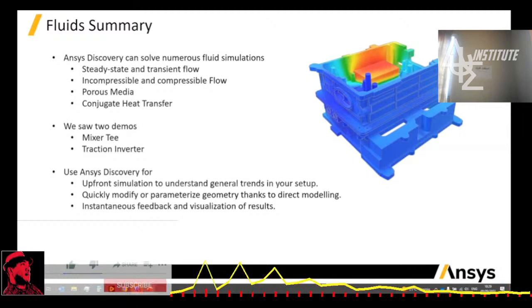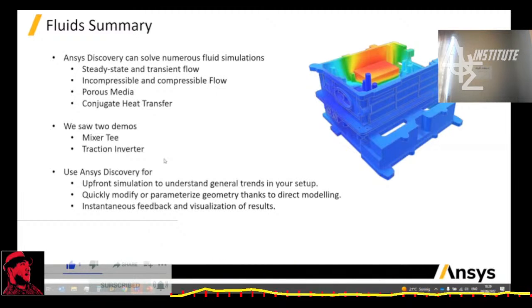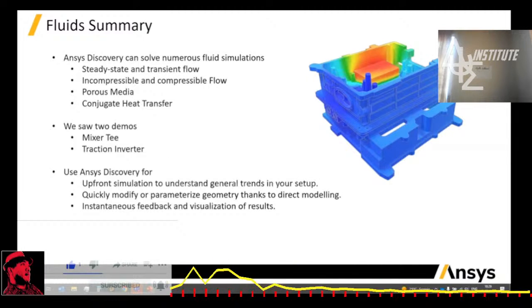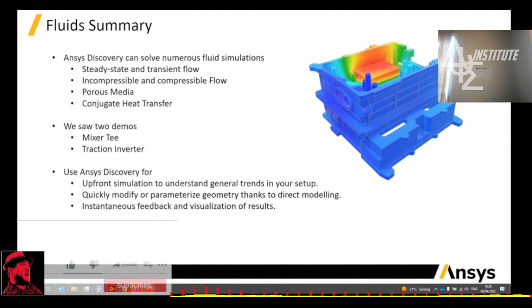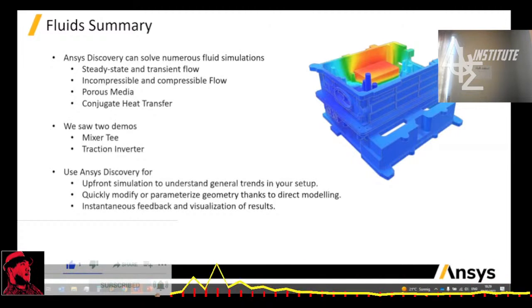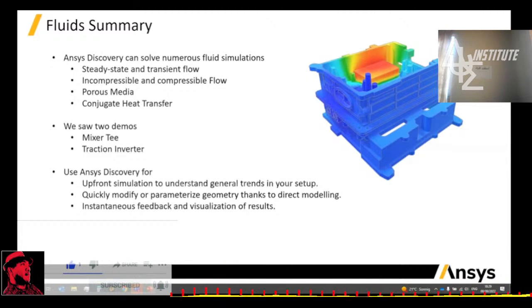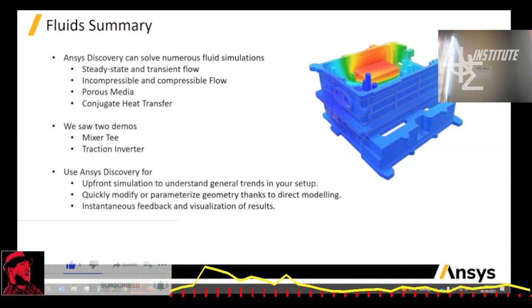Then we saw two demos today, one with a mixer T and a traction inverter, where we saw firsthand how to set up a fluid flow, first of all, important steps: extract the fluid volume, set up your boundary conditions, set up any monitors that you want to track, and visualize your results.